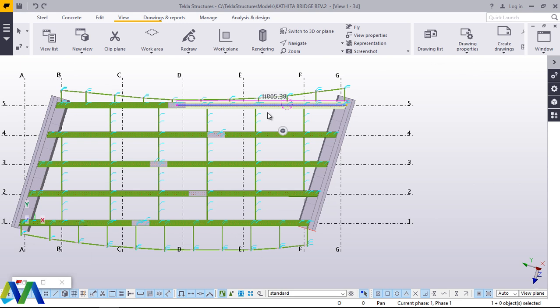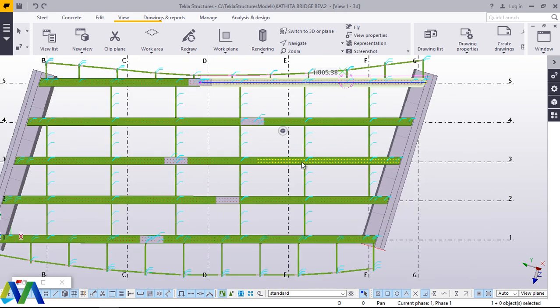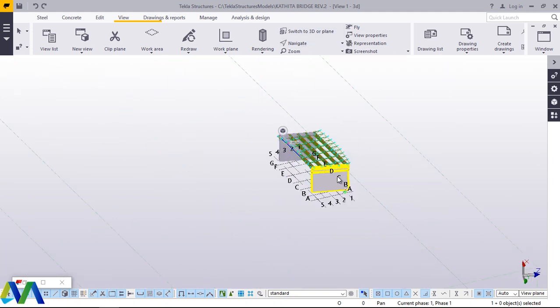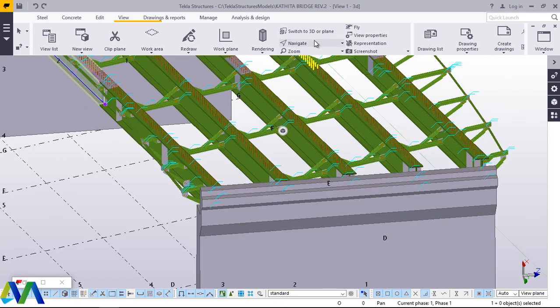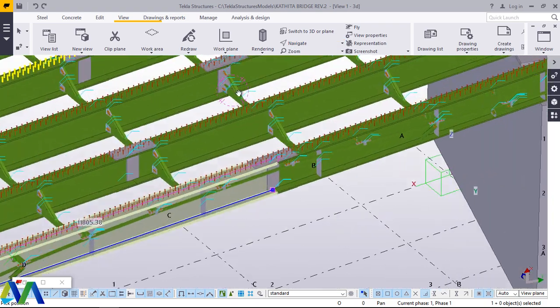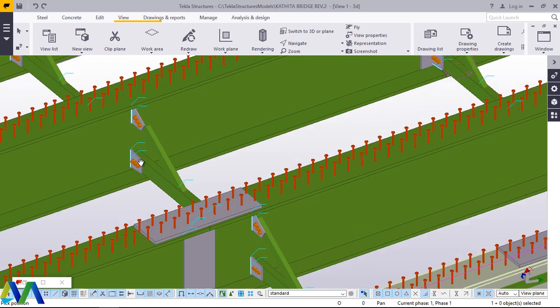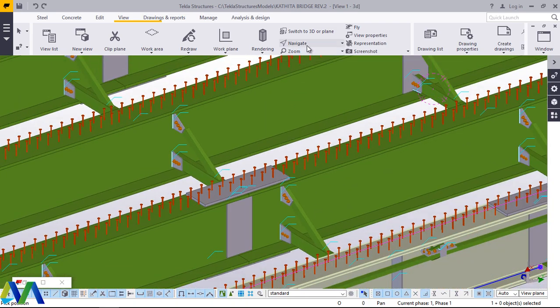That's my own design, and if you can do that, you can use either full length 12 meters, which is not really recommended, but it still works. But this was my approach. Now let's go to a full 3D of this. These are my main bracings that support the main girders for this bridge.